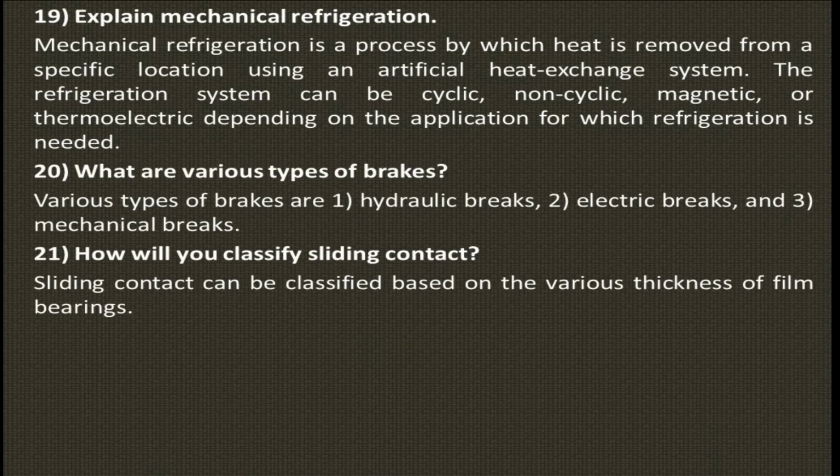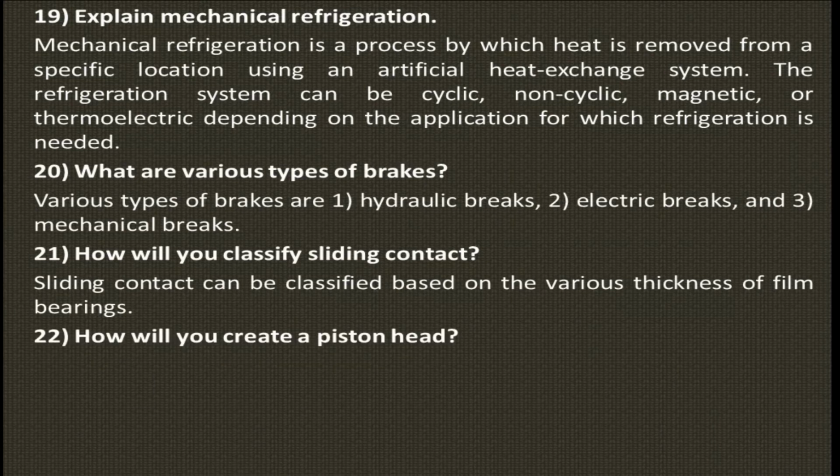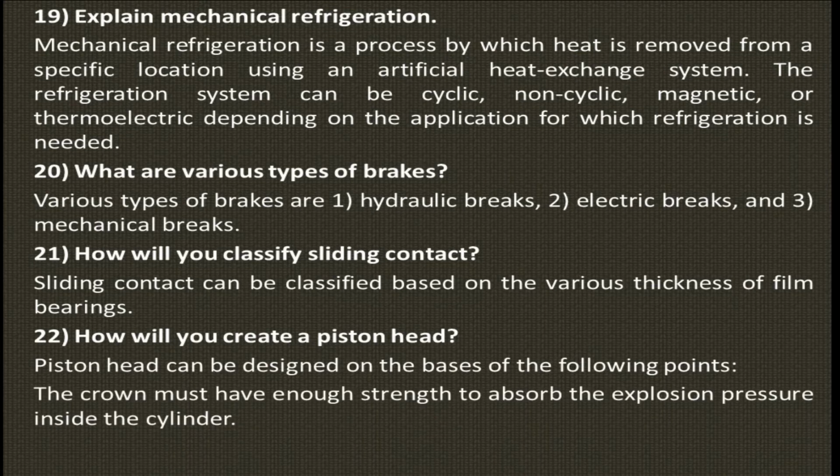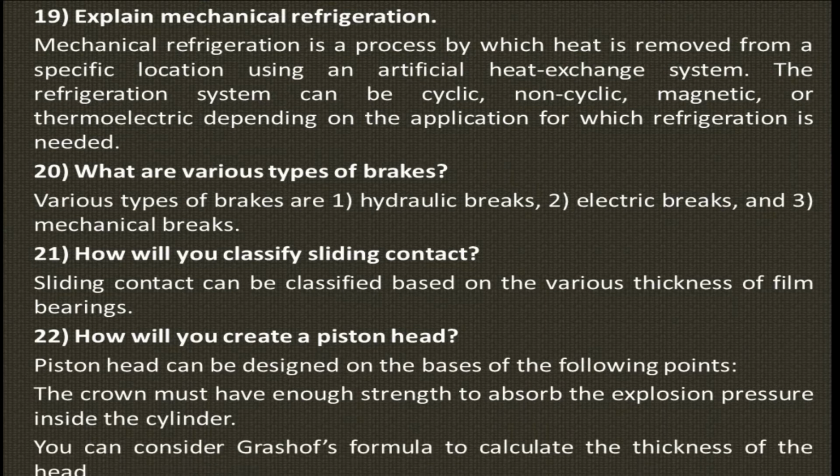Sliding contact can be classified based on the various thickness of film bearings. Question number 22. How will you create a piston head? Piston head can be designed on the basis of the following points. The crown must have enough strength to absorb the explosion pressure inside the cylinder. You can consider Grashof's formula to calculate the thickness of the head.